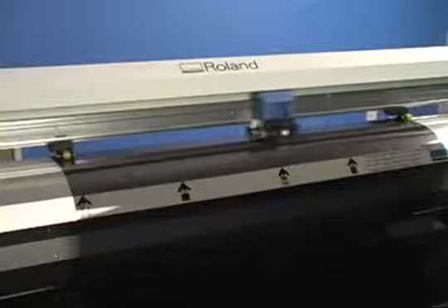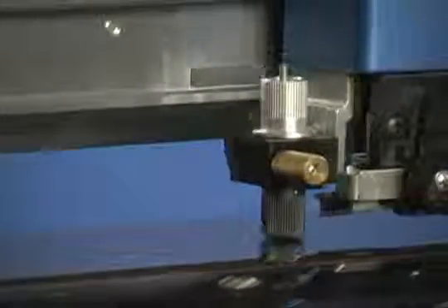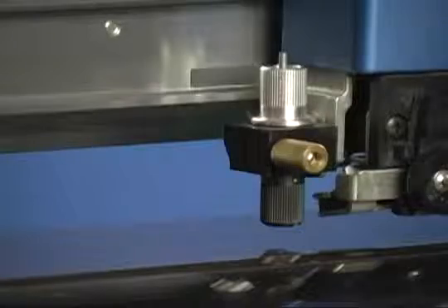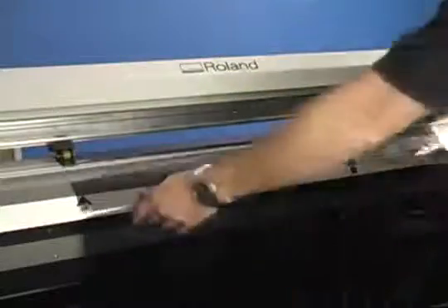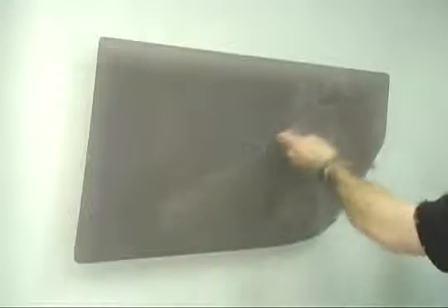Film Designs will cut the window film using a method we call cut on the pull. The blade holder only drops to the surface when the window film is being moved in one direction, providing for more consistent cuts and eliminating the possibility of the film bunching up in the cutter. When the cutting process is finished, remove the material. That's it! Simply weed the excess material from your pattern, and you're ready to apply to the vehicle window using a pre-mixed solution of soap and water.